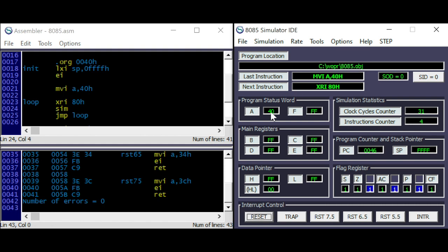So the value is 40. Do an exclusive OR with 80. So that's C, that's 8 and 4. The SIM sends the output to 1. Alternating the most significant bit again. It's 4. SIM, output is 0. So the alternation functions correctly.